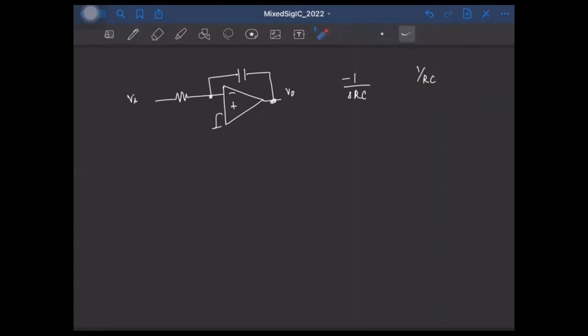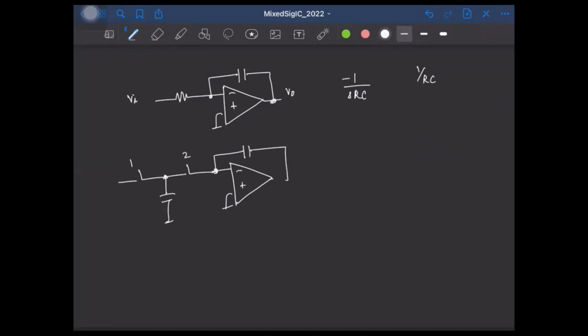So now we will try to replace this resistor by the switched capacitor we saw. Right, so this is the phase phi 1, this is the phase phi 2. And let's say we sample the output during the phase phi 1. Okay, so this is the clock. This is again phi 1, phi 2, and so on. And let's say I call the falling edge of phi 1 as the sampling instant. Right, so that's why I'm sampling the output also during the phase phi 1.